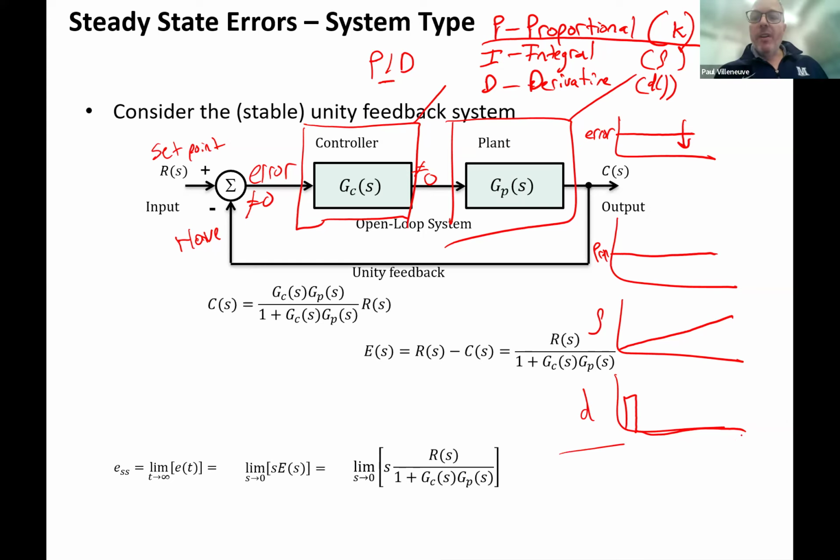So by adding derivative control, you actually will try to slow your system down. So you would subtract the derivative error, and then you hope that your proportional and integral are going to come in so that you can get the value that you want. So normally when you say PID, it's P plus I minus D. And the D term is only used on a sparing application.